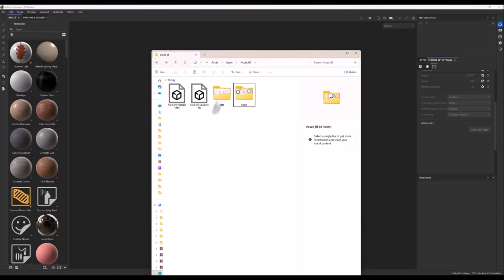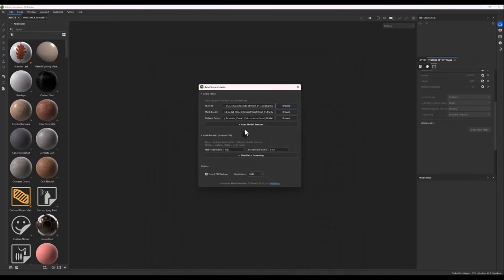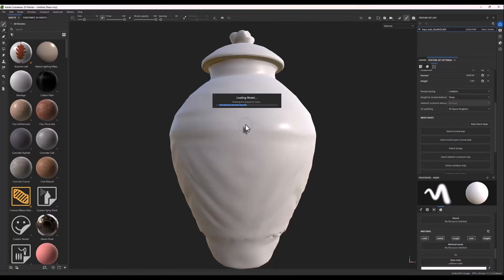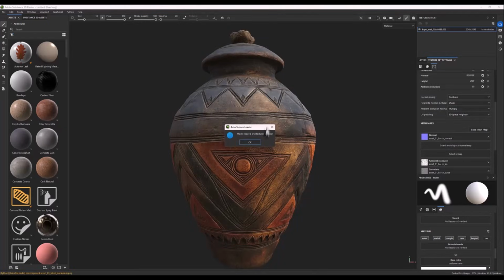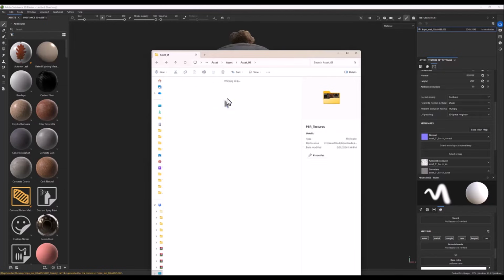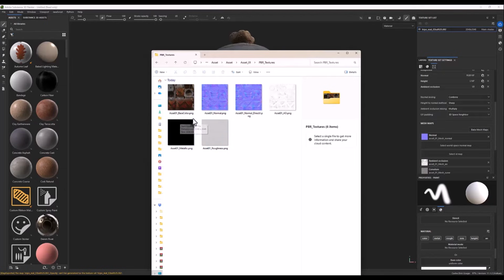So I hit load here again, and here an export step is also added to the work, and it takes the export for us. And look at the PBR folder here. It has been added. We enter it, each of the textures has been exported, a name has been given to it, the same as our folder name, and here it has taken the outputs for us. The PBR outputs: normal, ambient occlusion, metallic, roughness outputs.